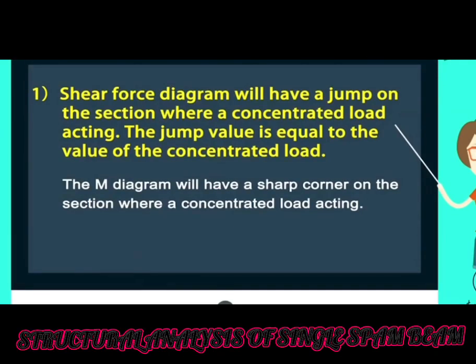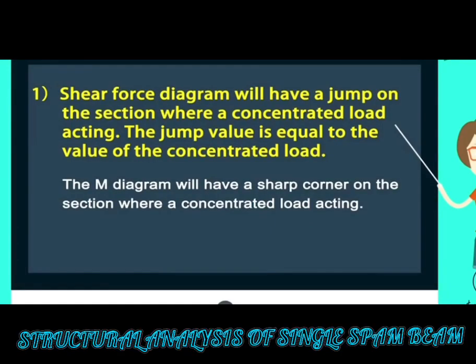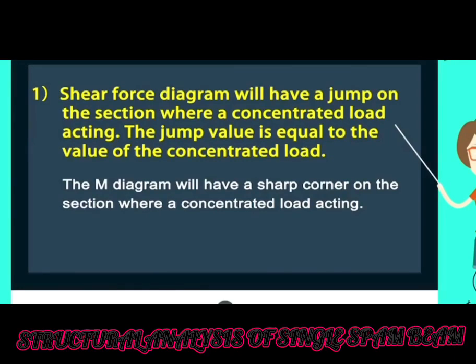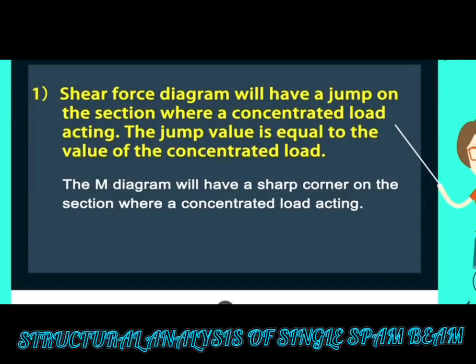The shear force diagram will have a jump at the section where a concentrated load acts. The jump value is equal to the value of the concentrated load. The bending moment diagram will have a sharp corner at the section where a concentrated load acts.